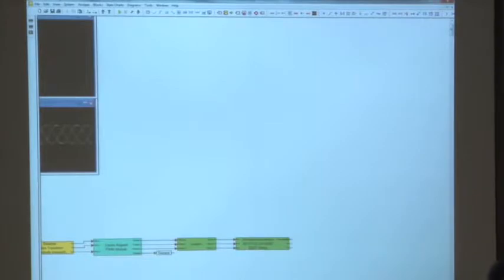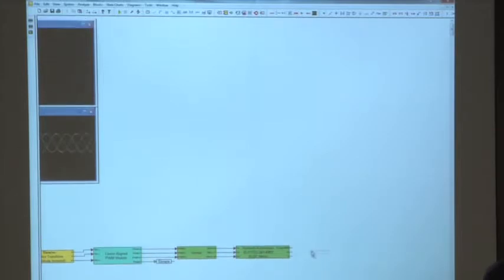Okay, now the output of the motor is going to have 3 variables. One is torque, one is phase U current, and one is phase V current. It's the same as phase A or phase B current, if you want to think of it that way. So I'm going to once again go up to the variable block, and drag down a variable block right near the output of the IU pin on the motor model.